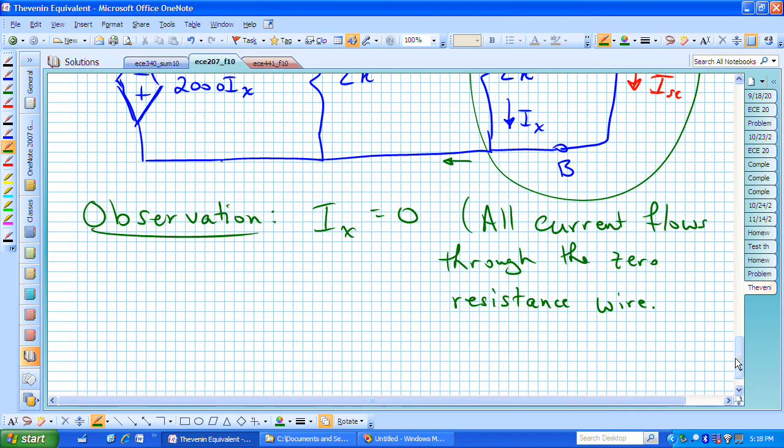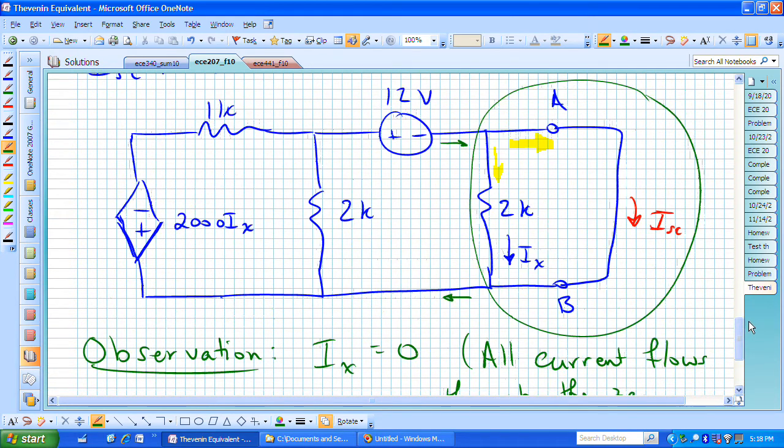If that's the case, then you can also, I hope, see that this forms a connection, and consequently this voltage source of 12 volts is dropped all across this 2K ohm resistor. And let me now label this as I sub 2, or maybe I should say I2.